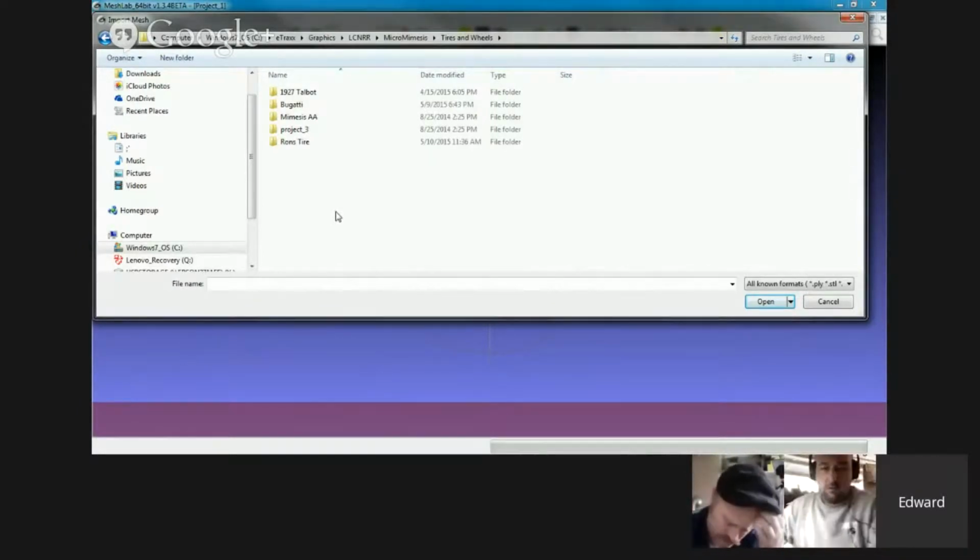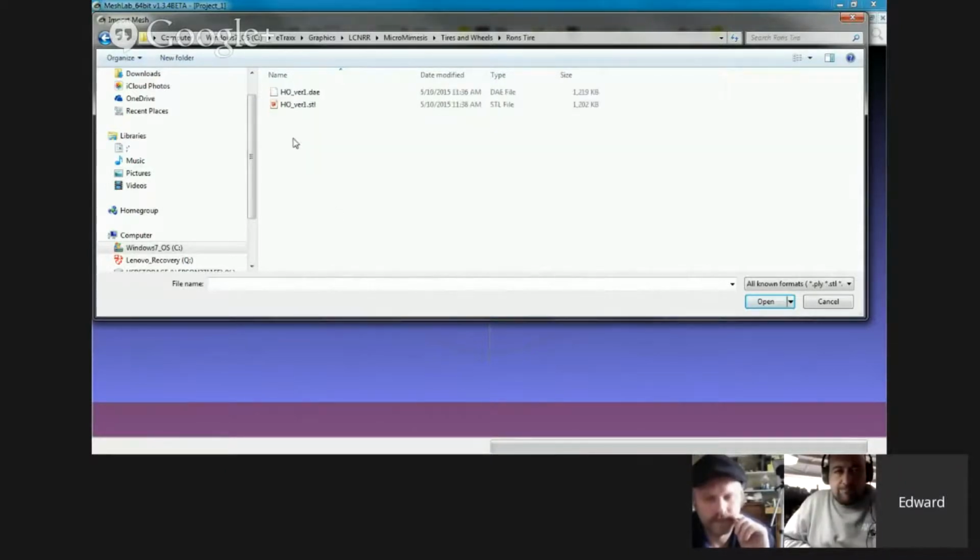Yeah, what I would do, I would make a tire with no tread, and then I would make a lug design for a tire, separately. I would intersect that with that face of that no tread on the tire. I would intersect the faces. Now I had a pie section with one lug on it, and then I spin that lug around 360 degrees to make my tire. So it's a little bit more complicated, of course, than that.